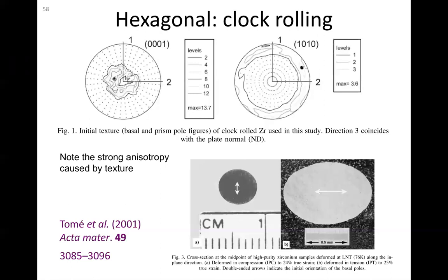And it's the takeaways that anytime you deform a polycrystal, or not even just deform, thermomechanically process a polycrystal, whether you heat it up or you deform it, you're going to alter the distribution of crystallites in your material, right?